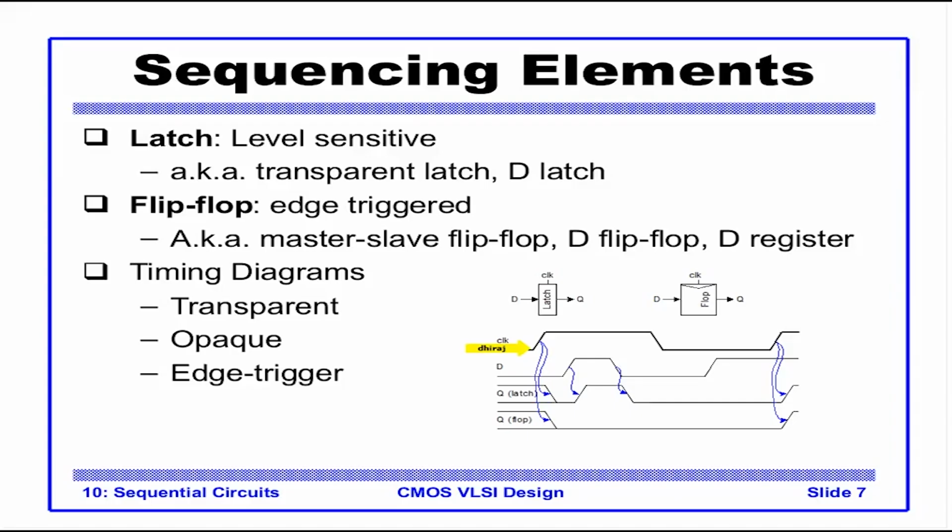That is, whenever the clock goes to 1, whatever is D is transferred onto Q. So Q goes to 0 after some time, and then nothing happens on Q irrespective of whatever is happening on D during the high pulse or the low pulse. The next trigger will only come at the next positive edge of the clock, when again D is 1, so Q goes to 1 after some time.